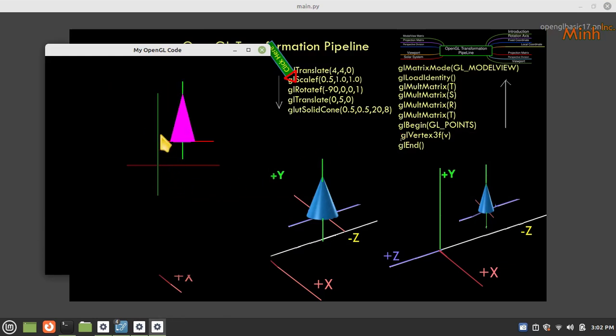Please mind that this global axis X and Y is gone. There is no meaning of X and Y. Now this local axis has come into the picture. Then top to bottom. Then scale. Then rotate. It will rotate along its own axis because that is the new axis.